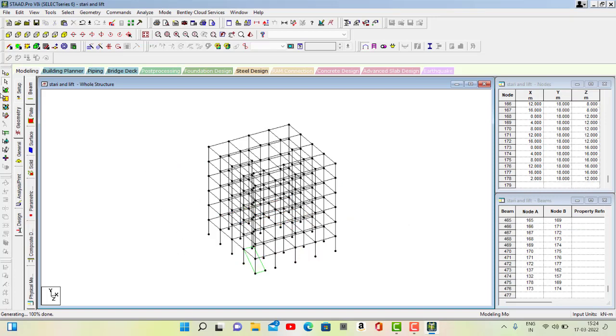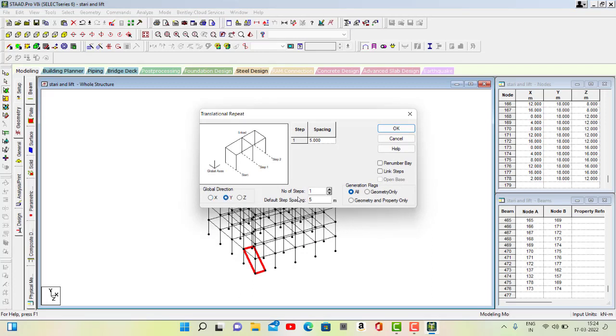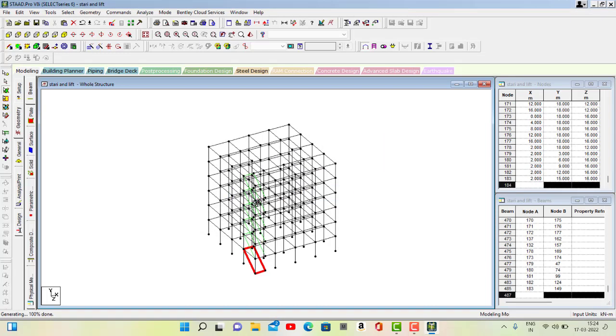And the next step is to select the plate circle and go for the translate limit and the Y direction. It will be consistent as the 5 floors, and we can change it to 3 meters height and click on OK. It will be a direct acting only. See, we can see how the plate was added here. This section we can see